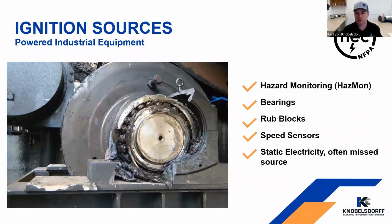So another ignition source that we deal with a lot, which is probably one of the most talked about ones, is just powered industrial equipment, right? So your bucket elevators, your drag conveyors, belt conveyors, screw conveyors. The best thing that we can do to protect from ignition sources on this type of equipment is through hazard monitoring. There's been a lot of companies with big initiatives over the last 3 to 5 years, and some even longer, to make sure that all of their equipment has hazard monitoring detection. So bearing sensors, alignment sensors, speed sensors. Static electricity is often one that gets missed as well, that can affect you on your pneumatic systems and any points of transfer between systems.